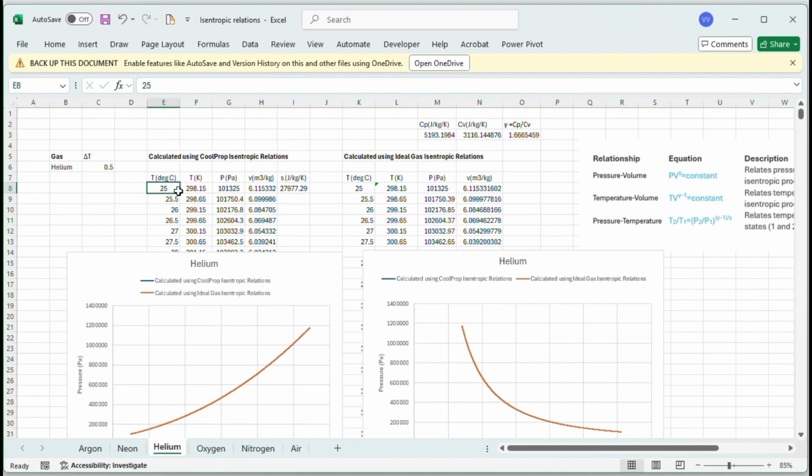So for the initial temperature and pressure, you calculate the entropy. For the next temperature, the corresponding pressure is calculated based on the same entropy. So you're using this entropy as the input. So using that entropy, and for the new temperature, what will be the new pressure? Okay, so basically what that means is all of these will have the same entropy.